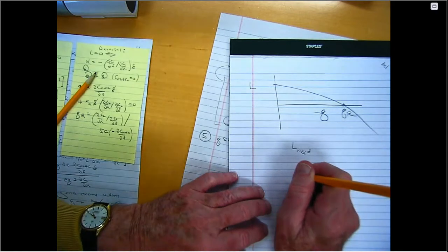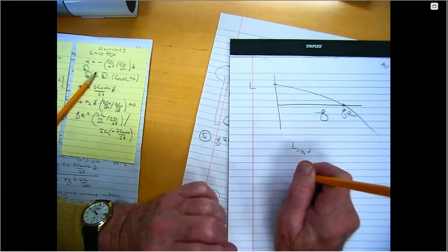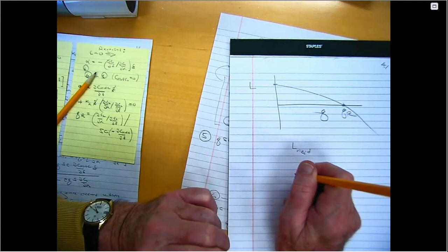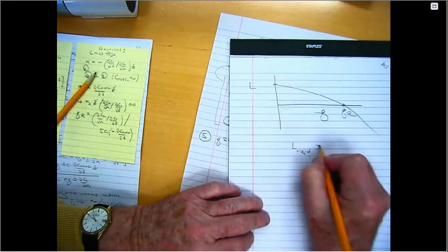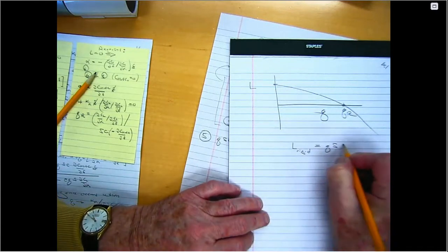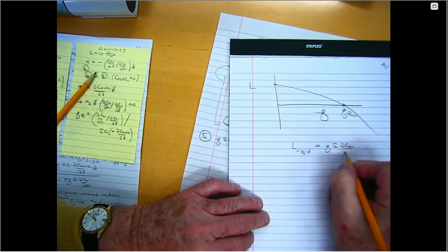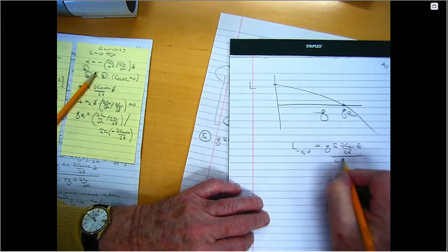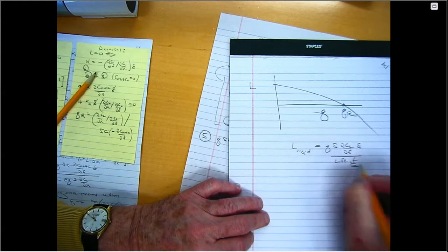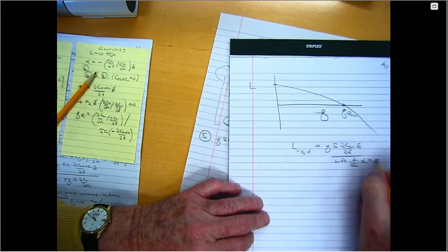Assuming that there's no elastic or aeroelastic effect, right? So that would be just Q S dC_L/d delta times delta. This is the lift if alpha is 0.